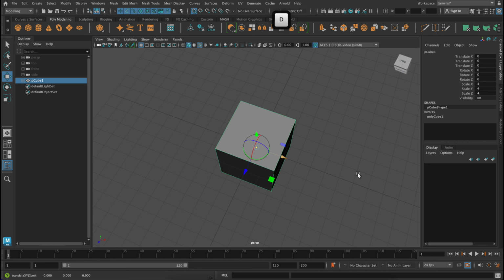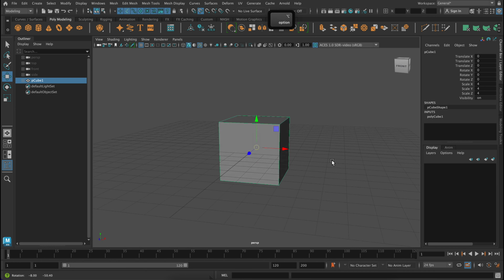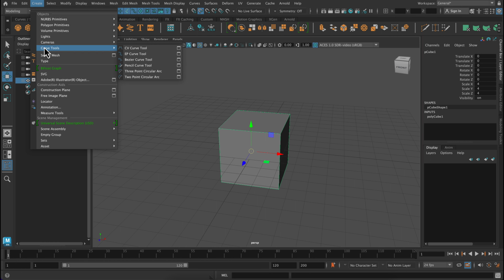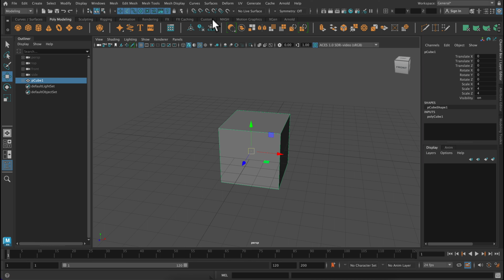So that's grid snap. The next one is snap to curves. So if I turn that on, and I barely ever use this one, by the way, if I hold down D, and this time I'm going to move using my Move Multi-Ways tool, it really doesn't actually snap to anything on my model, and that's because these are edges and not curves. So a curve would be an object that we would make out here. So we don't really use this one.